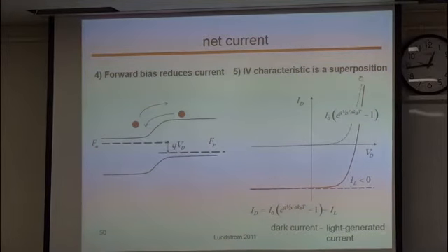Usually when we use the AM0 solar spectrum, we will get this kind of curve. But if we use solar light with AM 1.5, then we will have the following red line in the IV figures. Based on these curves, we can measure the efficiency of the solar cell.